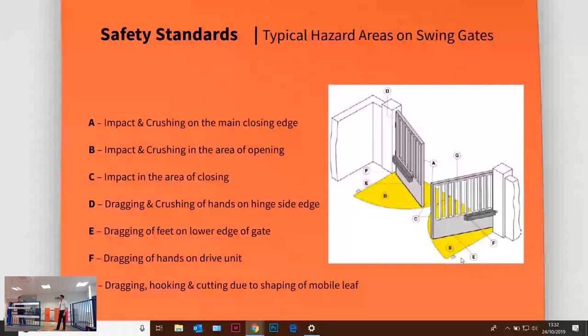If you're doing retrofits especially, it's something you really need to take into consideration. There are some safe gaps which we're going to be looking at a little bit later to give you more detail on this point. So what we're looking at for the protection on the hinge point, ideally you design it out, so you remove it. If that's not possible because it's an existing gate, then you're trying to use, for example, safety edges on the gate, like active safety edges, so they are responsive. And lastly, if none of that is possible, you may only be left with using a finger guard.